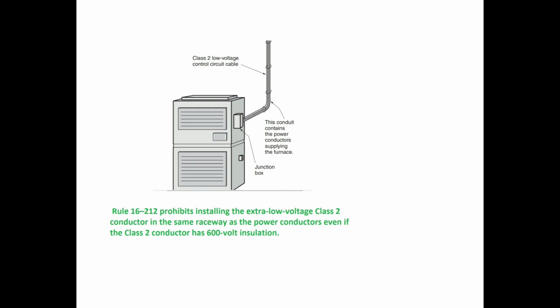For example, a #16/4 LVT cable at 35 degrees Celsius has the following ampacity. Temperature derating from Table 5A, Column 2: 10 amperes times 0.82 equals 8.2 amperes per conductor. Table 57 correction factor for 4 to 6 conductors: 8.2 amperes times 0.8 equals 6.56 amperes per conductor.